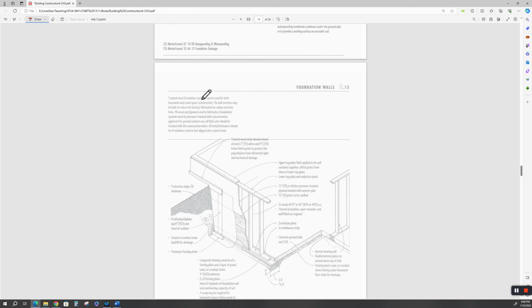Treated wood foundation systems. If you do a subterranean treated wood foundation system for me, I will fire you in a heartbeat and try to get you committed. This is a haven for everything from termites to rot. And there's all kinds of different rot. There's direct water rot, there's dry rot, which is wet and dry cycling. This is just a bad, bad, bad, did I say bad? Design. Don't do it. Don't do it.